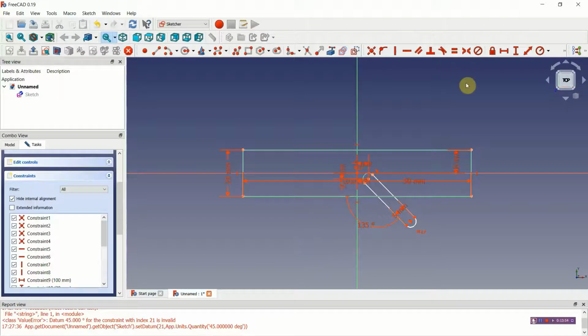We can now clean this up a bit. We use this trimming operation to delete this, this, and this. The last part, a right mouse key to stop those operations, then we click over this, drag a box over it, and the delete key, we can get rid of that.